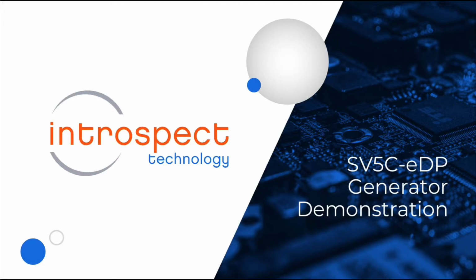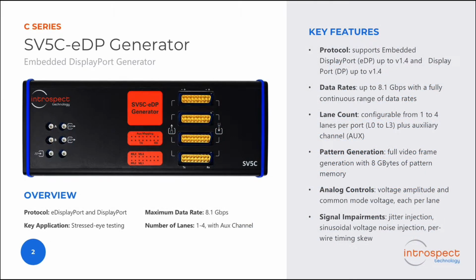To introduce the product, here's a quick overview of the key features of the SV5C embedded DisplayPort generator that we'll be looking at today. As you can see in the key features on the right, the generator supports embedded DisplayPort and DisplayPort, each up to version 1.4. Lane counts can be configured from 1 to 4 per port and includes the auxiliary channel. Full video frame generation is also possible with 8 GB of pattern memory available. The SV5C also provides unique analog controls and signal impairments for stressing a DisplayPort sink device, including per lane voltage amplitude and common mode voltage control, as well as jitter injection, sinusoidal voltage noise injection, and per wire timing skew.